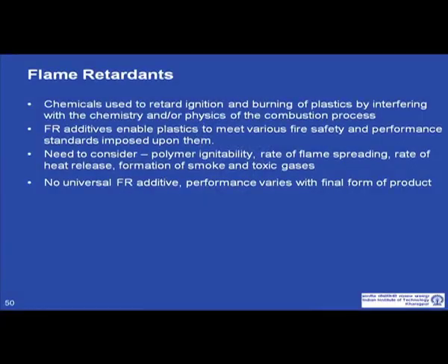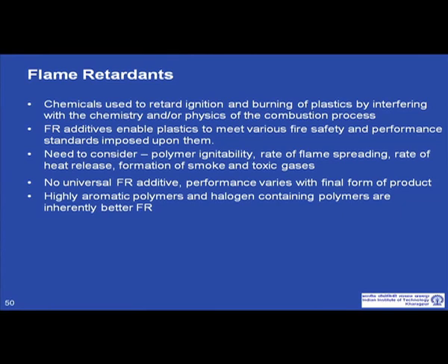The choice of fire retardant additive depends upon the polymer-additive pair. One additive may be very good for one polymer, but the same additive may not be as good for other polymers, so it is essential that the combination is chosen rightly. The performance also varies with the final form of the product, and generally highly aromatic polymers and halogen containing polymers are inherently better fire retardants.